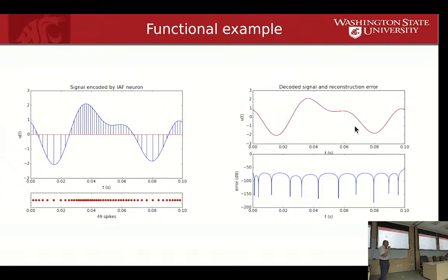You feed the spikes back to a reconstructor, the same way you do with Shannon, and you get a reconstructed form of the signal. It's very difficult to see the two, and this is a graph that engineers would love very much, where you can get the reconstruction down to minus 80, minus 100 decibel, which means very, very high quality reconstruction.